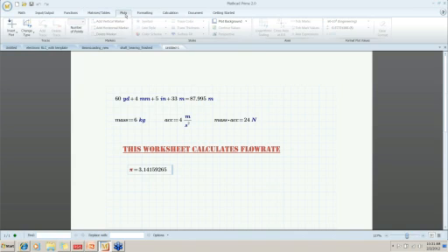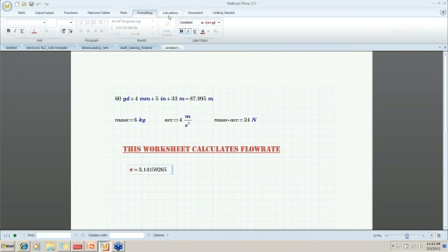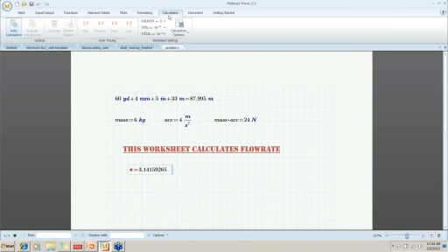This is your plotting tab. You can format plots very easily by just coming to the plotting tab and clicking on the category here and clicking on what you want to do. So changing the symbols on your lines, adding traces, removing traces, adding markers, all of those sorts of things are here. Changing the color of the lines and the style, things like that. We already covered formatting. This is the calculation tab. This is where you can turn automatic calculation on or off and control how your worksheet calculates.